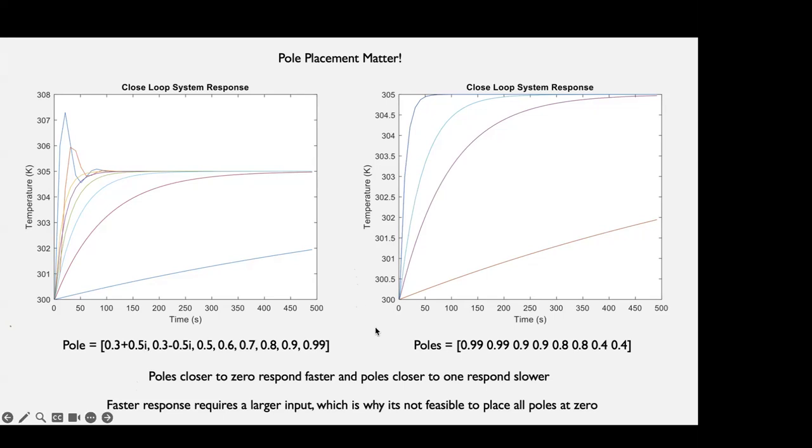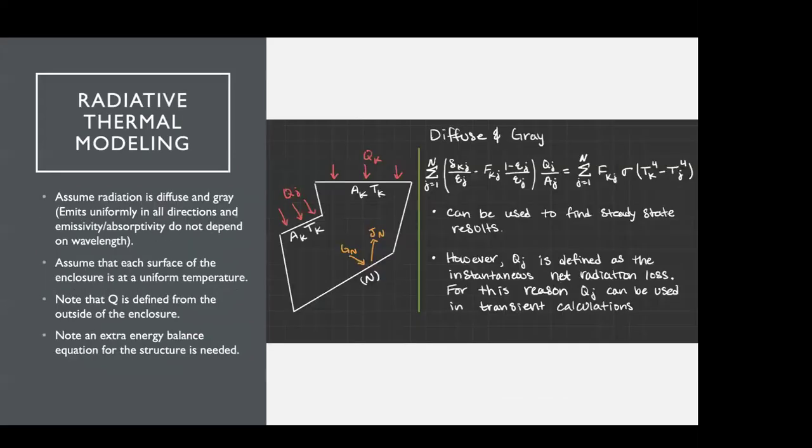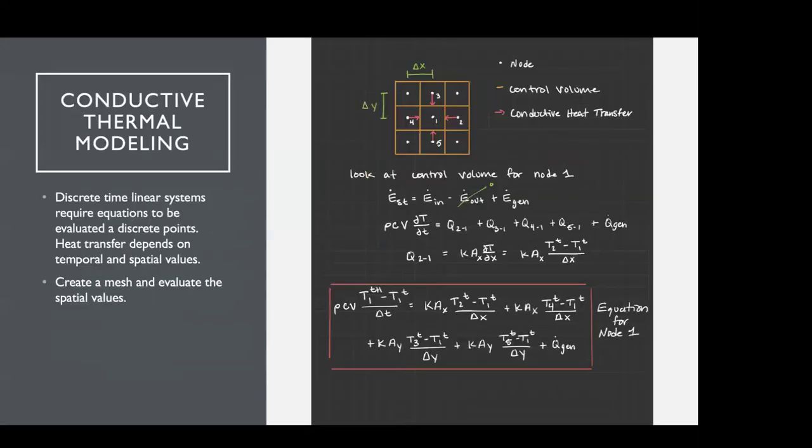In your conduction finite difference model, do you have a full mesh or do you have elements, and how do you handle empty space? What do you mean, empty space? For example, if you have an enclosure in your CubeSat, the space in between is empty, it's not conducting, so do you only conduct within your CubeSat, or is the whole space meshed?